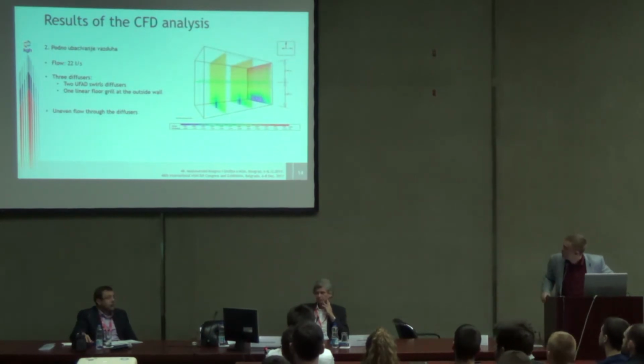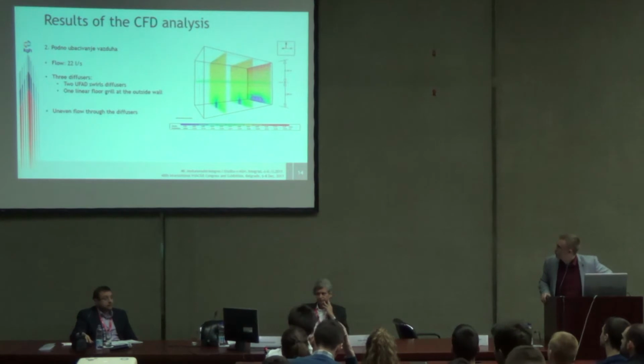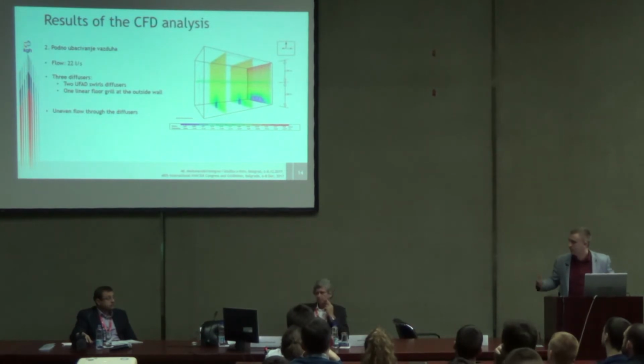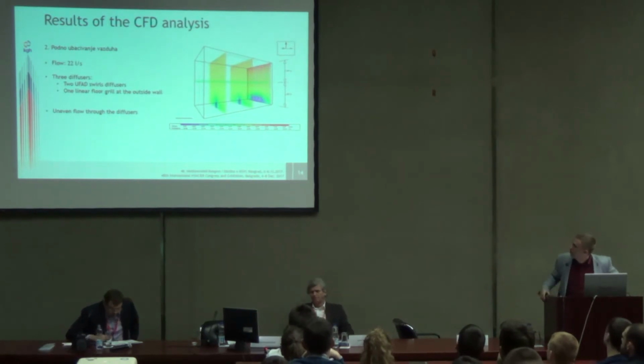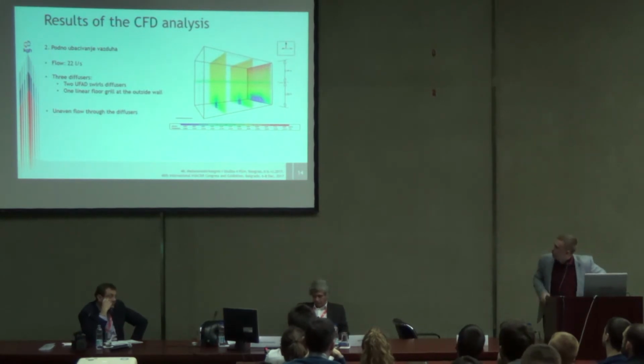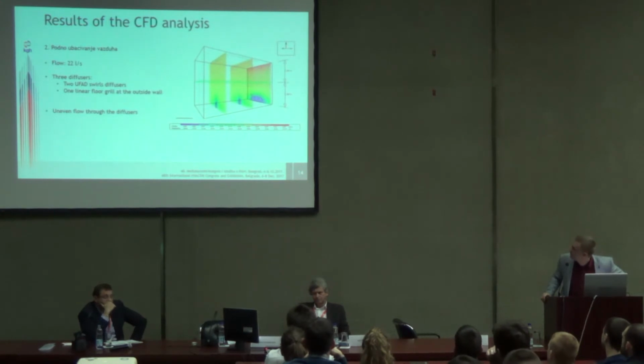You can see the same situation and a pretty good air distribution, and the stratification, which is the best part of underfloor air distribution. You can see the height of 1.85 meters, which according to ASHRAE 62.1 is the occupied zone. We have pretty good temperatures in this zone. The yellow color is 22.5 degrees Celsius, which is pretty good.